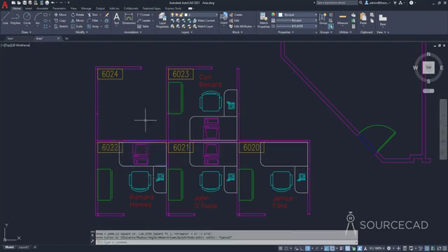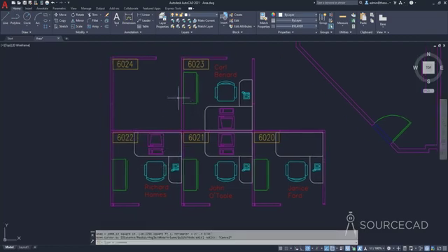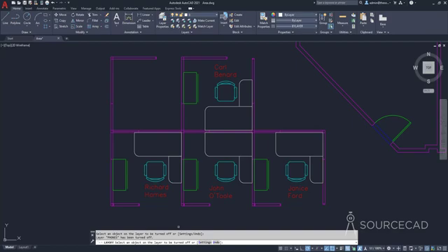So in this case, I'll just hide the blocks. And to do that, I'll go to this layer off option and I'll hide this block, this one, this one. That's it. And then we are ready to find the area. So I'll just go to this Quick option and I'll select here, and you can clearly see the area here on the tooltip. That's 2102 square inch or 14 square feet approximately, 14.6.